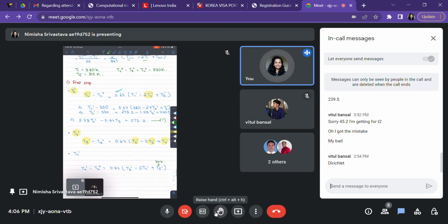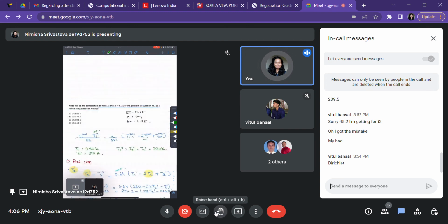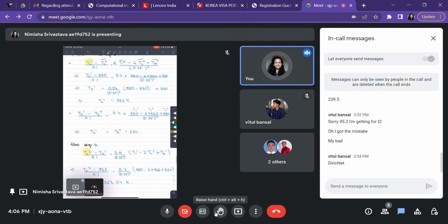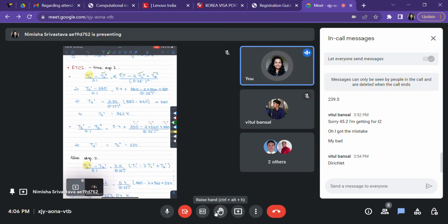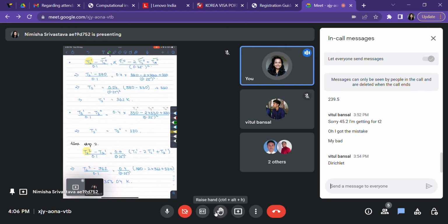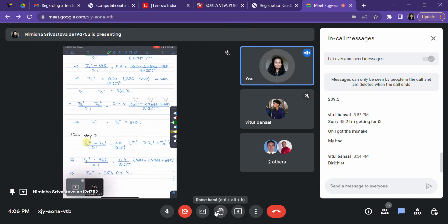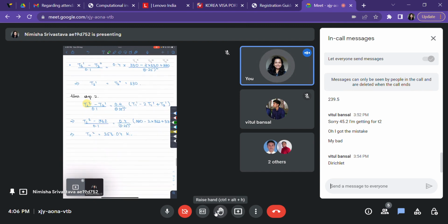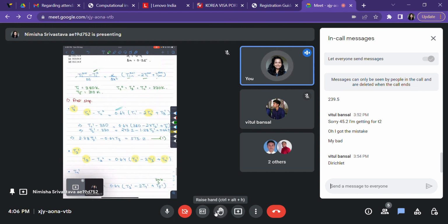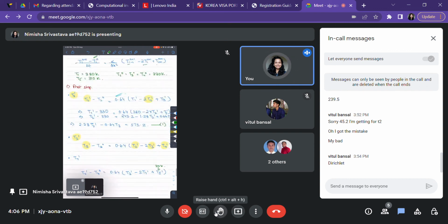But essentially, the difference between the explicit and the implicit method is that in the explicit method, you could just simply plug in the known values and you were done. You were able to calculate the temperature at the node that you needed. Okay, you just needed the equation for that node plus the neighboring one. So that's about it. But here you will have to go through the entire domain before you even start to get a solution. So you're going to get a system of equations rather than any particular value. So I'm going to conclude the class for now.